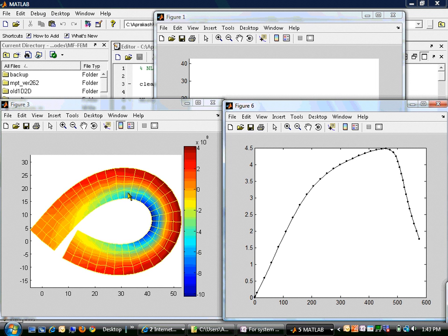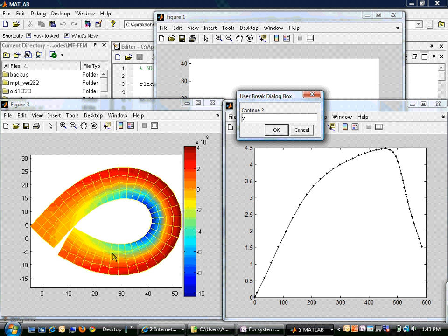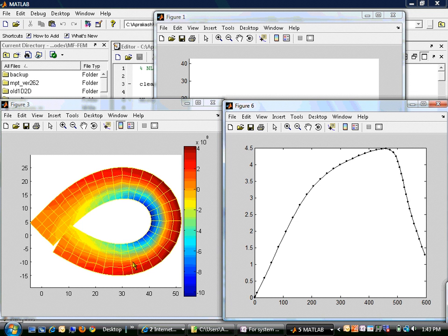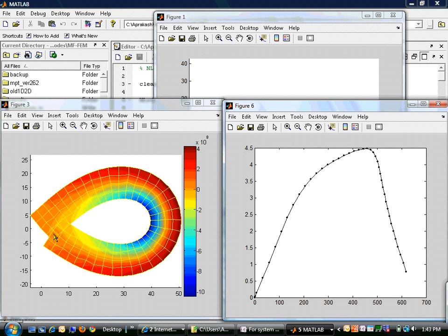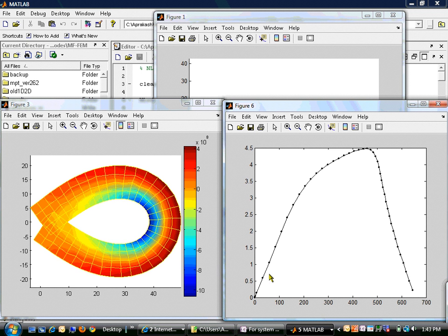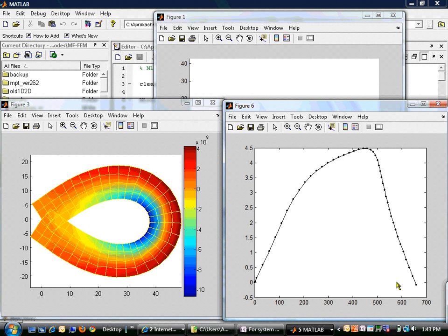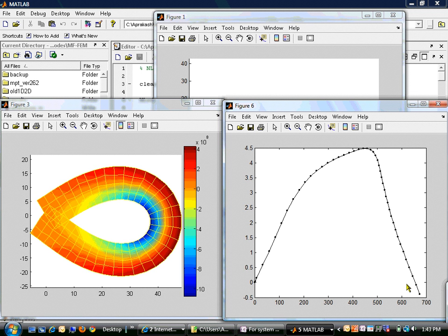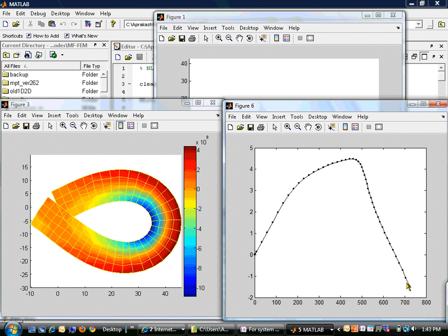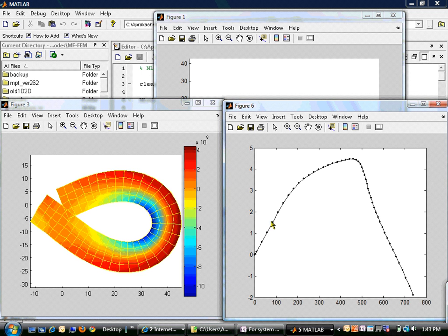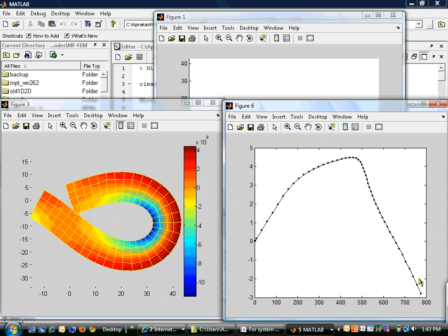And now this beam is going to snap around. So you can imagine this is a rubber beam, and if you keep on increasing moment, at some point it will snap, and it will start to take all that load in the opposite direction. But just to tell you that even in Abaqus, if you are using nonlinear procedures, Abaqus might compute to quite a long distance.